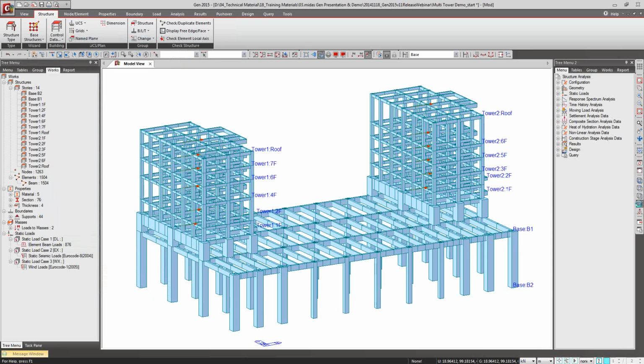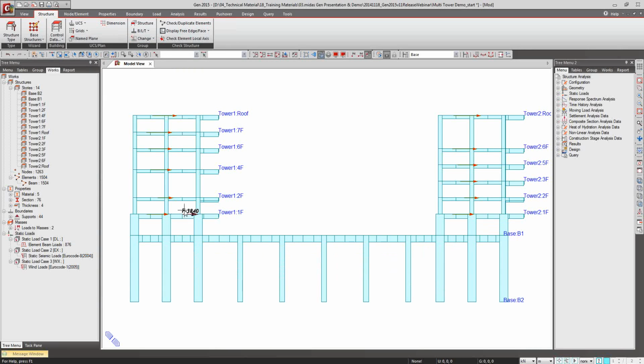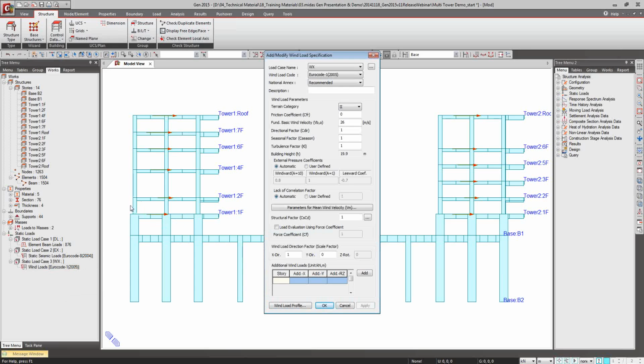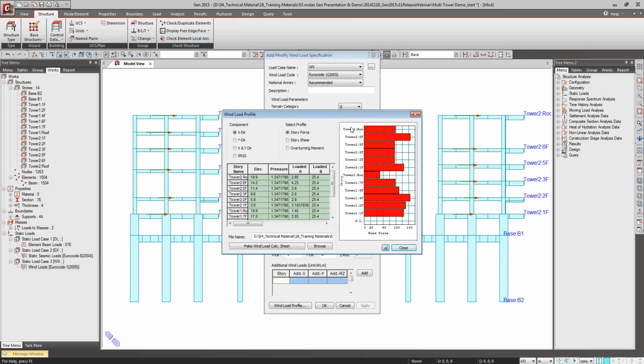And if we click OK, for each of the towers, this static seismic load is entered at the mass center. Similarly for the wind load, which was using the dimension of the below level. Now we have the different towers. The program can recognize their regions.